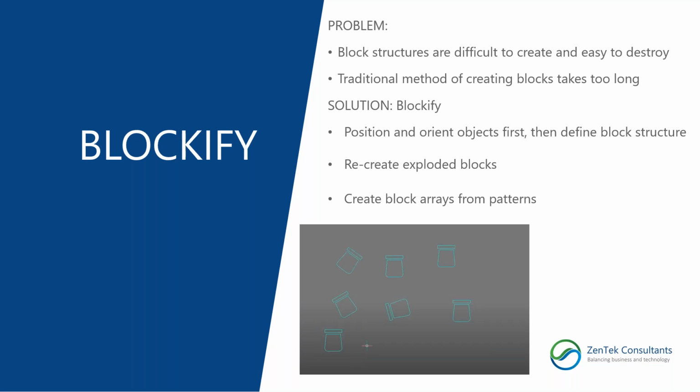As most of you probably know, when you create a block, all you're doing is combining a bunch of objects into a single grouping, which you can then insert as a unified group. To undo that, a lot of times people can go into the drawing and explode those blocks.